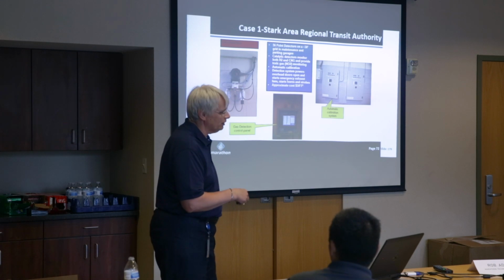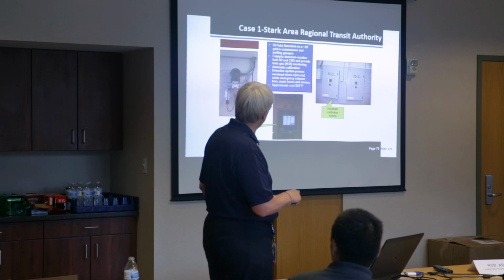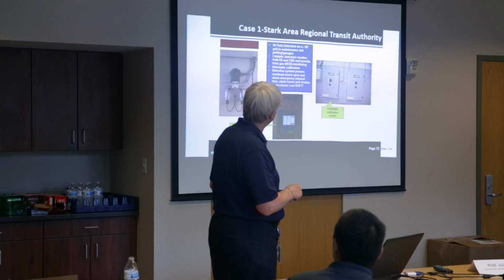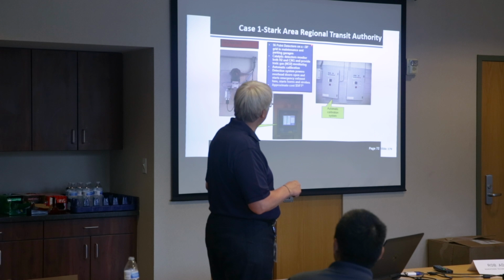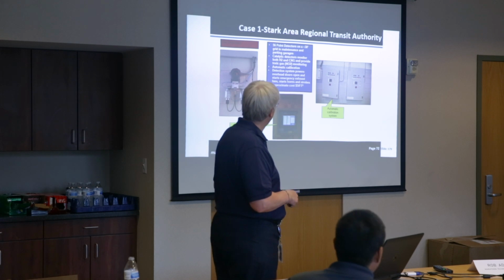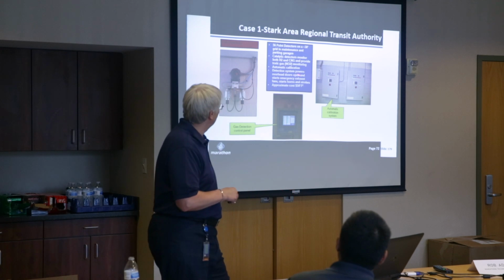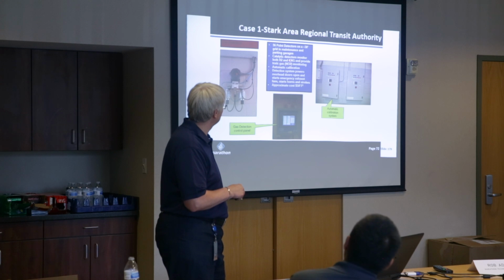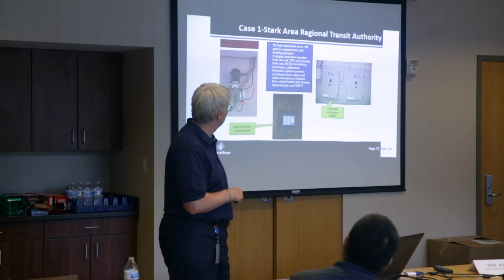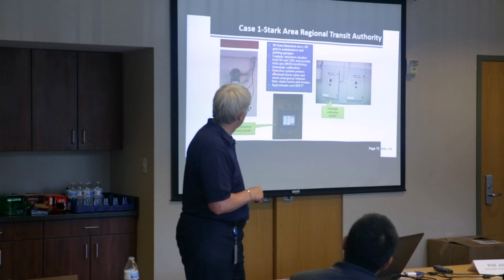You're going to see this. Actually, I should just skip over this slide. This is Jim's stuff here. Jim is going to give us a description of how his system works. But basically, 56-point detector, stop me if I'm wrong here, on a 30-foot grid. And I think that 30-foot grid is not hard and fast. Yeah, it's a little bit larger. They are catalytic detectors, and they're set up to monitor both the hydrogen and CNG, and then you've got toxic gases here as well, correct? Yeah, CO. Just CO? Okay, just CO. So I should fix that.